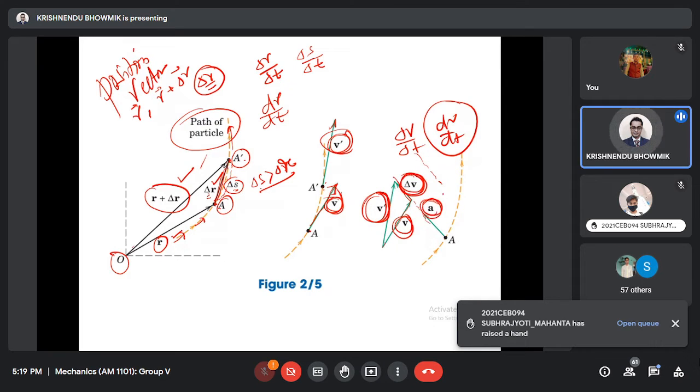Now this acceleration may be two things. Any acceleration can be like this: A, it will be ax, ay. We can have x and y directions decomposed, or maybe if this is the A, somebody can have a normal component an and a tangential component at.